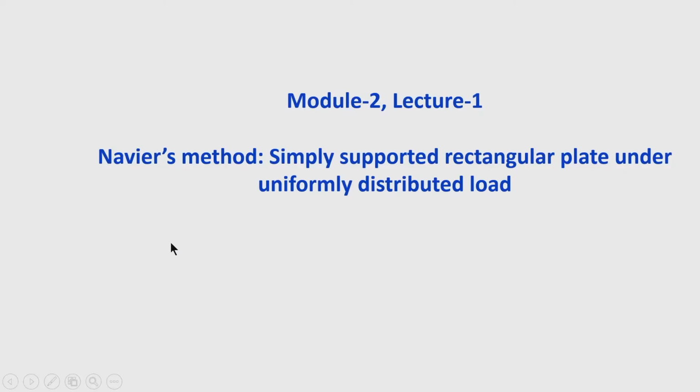So, today I will discuss a method for rectangular plates that was developed by Navier, and with the help of this method we will try to find the exact solution of the differential equation. Navier's method is applicable for plates simply supported along all edges, and it is especially applicable for rectangular plates. Today I will discuss Navier's method for uniformly distributed load and also partially covered load.